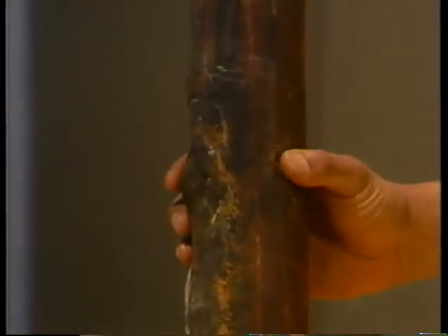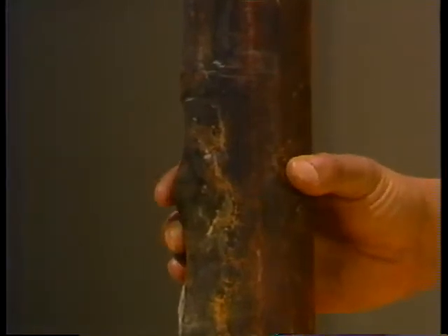Heat blisters, also caused by overheating, only affect one side of the tube. Heat blisters always indicate the presence of waterside deposits. Waterside deposits insulate the tube from cooling flow and cause the tube to become overheated. The blisters are formed when a portion of the tube metal becomes so hot that it softens.